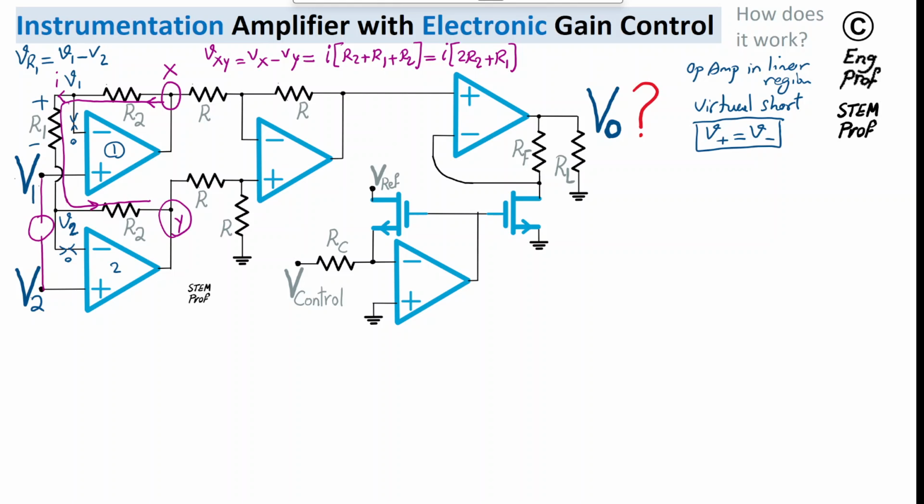So that's why, let's say, that sensor is applied between V1 and V2 connected to the positive input terminals of the op-amps, so no current is being drawn from the sensor, and we just sense the delta V over the sensor as V1 and V2, and that's how the circuit input is received from the sensor. So that could be one example.